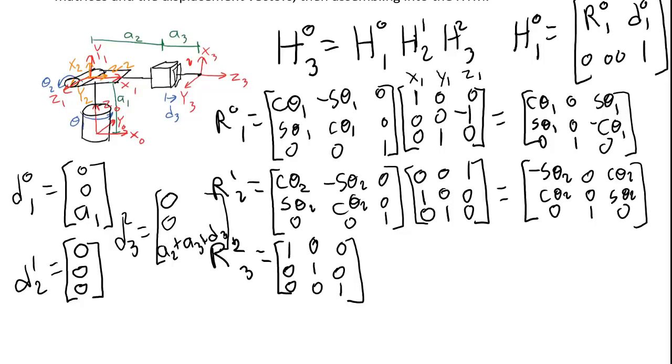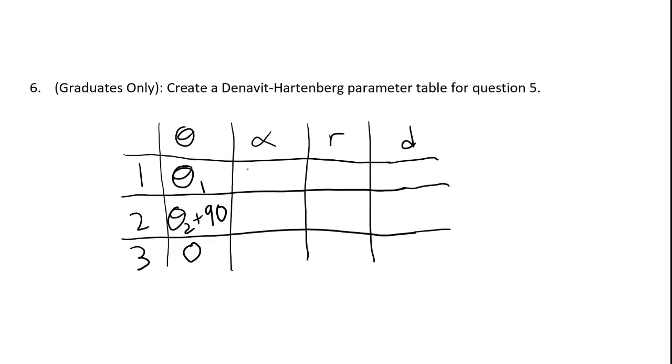I also have to think about whether this rotation is positive or negative. So I put my thumb in the direction of x1, and the direction that my fingers curl is telling me the positive direction of rotation. So the direction that I have to move z0 is from up to out of the page. That's a positive rotation around the axis x1. So alpha for the first row is 90 degrees.